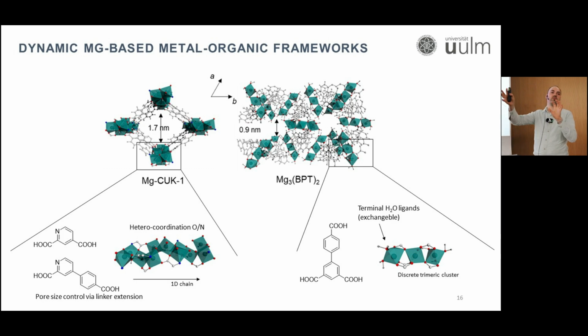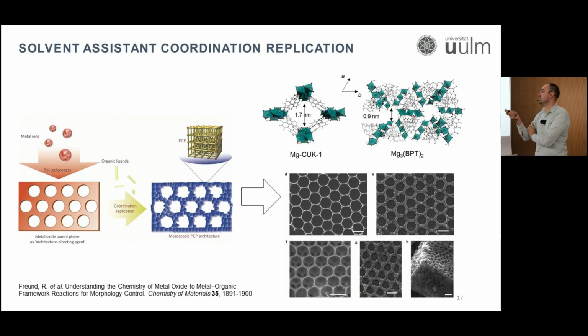This gives the system more flexibility in all 3 dimensions of the crystal lattice, which is something that is pretty critical for the electrolyte system, because we cannot control the directionality in which the crystals are immobilized. And so in this case, in worst case, your ionic transport will happen perpendicular to the pore channel. So we have a 1-dimensional porous system versus a 3-dimensional porous system, both featuring responsive or dynamic building blocks.